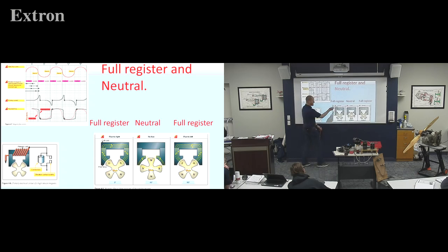And then inside this flux field, we basically have our secondary coil. When this flux field collapses across that coil, that's when we generate a huge voltage on the secondary. It does, because in neutral position the flux is down at the bottom. So you're stopping the flux, which is collapsing the field, inducing. Well, it's a change in flux with our magnet that creates our amp draw on the wire. Once we have amp draw on the wire, that is going to want to either build or collapse.